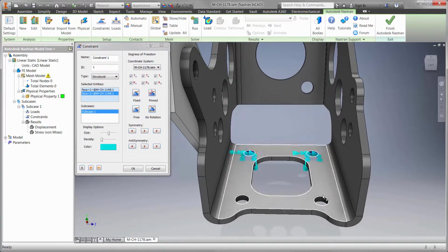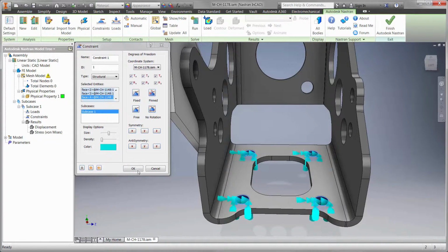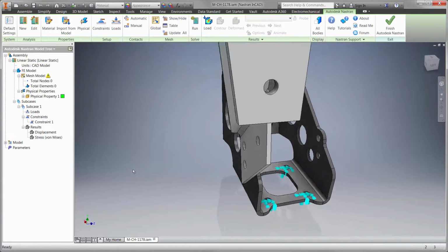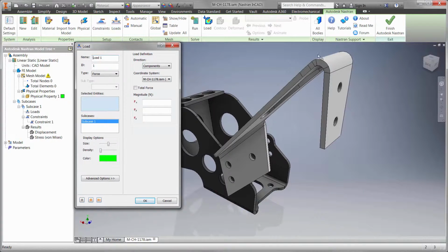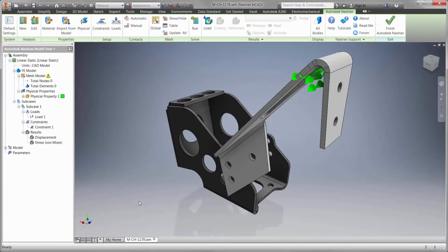We'll begin by holding the cylinder mount down to the pedal box base. Each of the boundary conditions provide great visual feedback for the type and location. Next, we'll apply the load to the clutch rest. Our goal is to withstand a force of at least 600 newtons, or about 135 pounds.